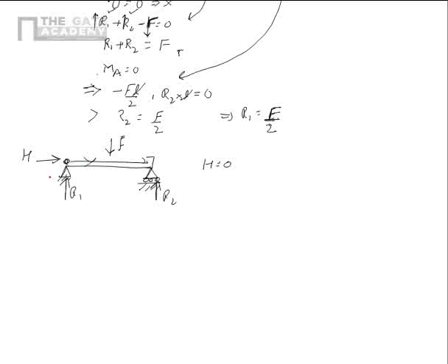Now this motion is also cancelled out. Hence, if there are two roller supports, that is not going to help you. That is obviously not correct. We have to have one roller support and one pin. This configuration of beam is called simply supported.